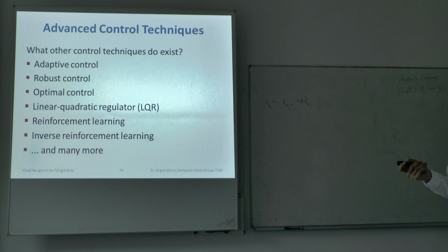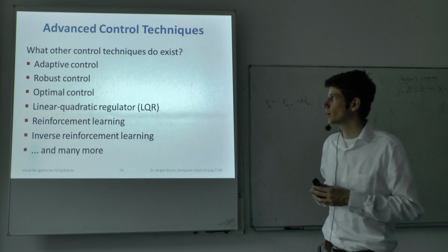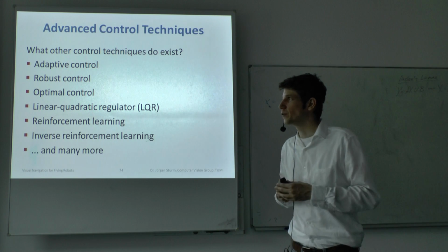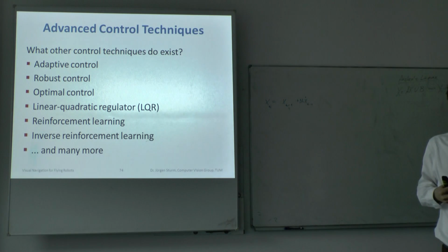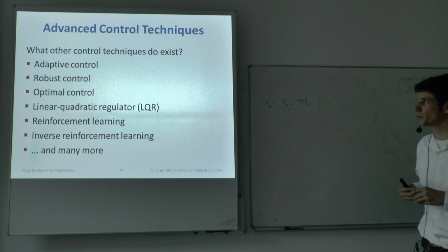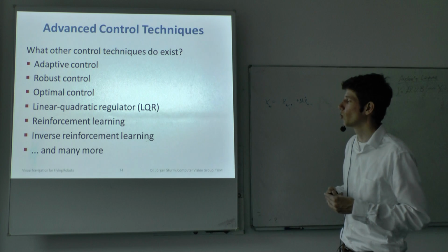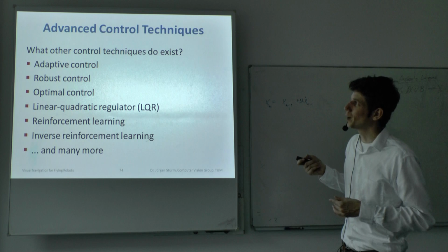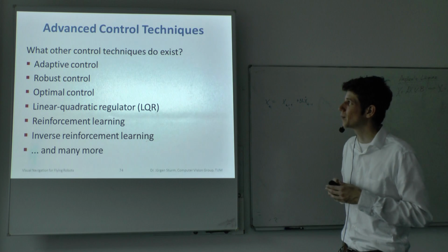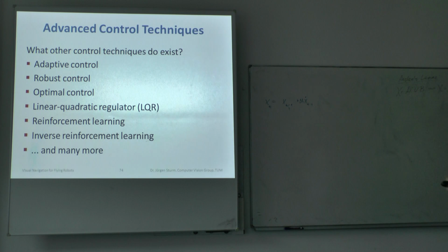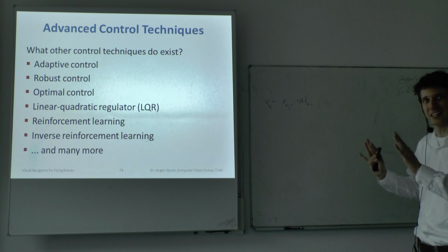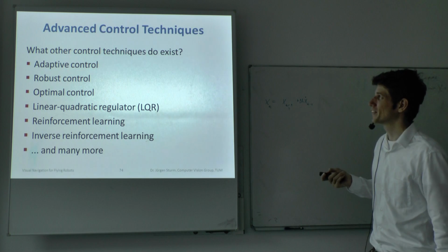Another domain is called robust control, where you do not try to achieve the desired value as fast as possible, but make sure that it even works if there is substantial noise on your signals, and potentially changing noise. For an airplane, for example, you maybe do not want the very best control or the fastest convergence, but you want to make sure that even if one of your turbines is suffering a small problem, you still don't start to oscillate.